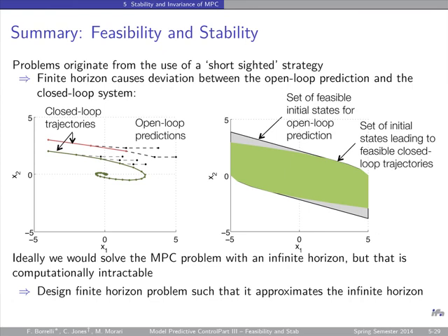So there was another set, which is the green set. We call this set calligraphic O infinity. It was the maximum invariant set. We'll discuss this set today a little bit more in detail. The infinity in there stands for it's feasible at all time steps, from 0 to infinity. That's why there is an infinity sign in there.